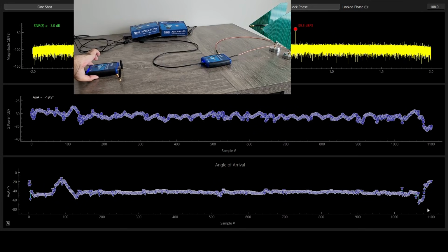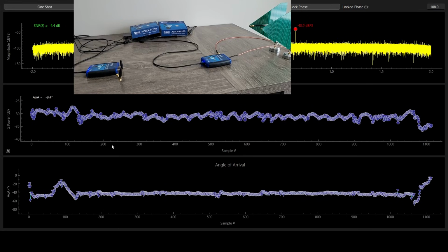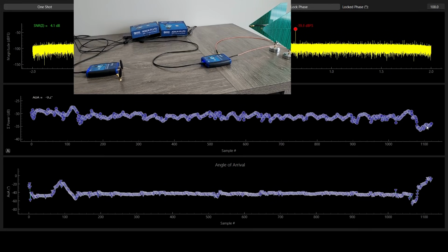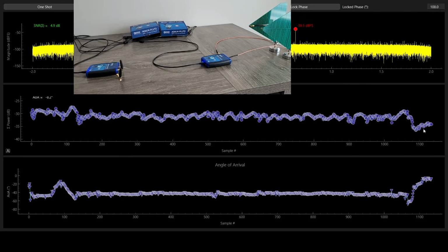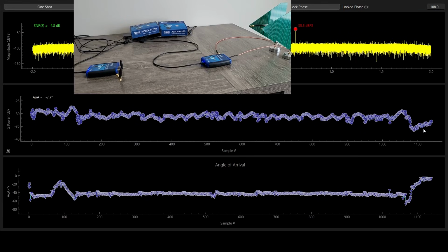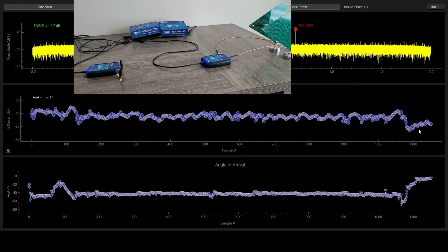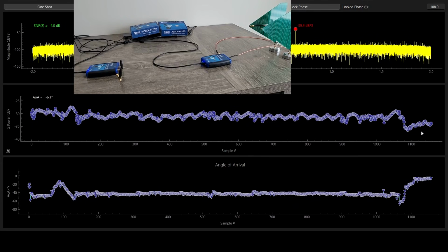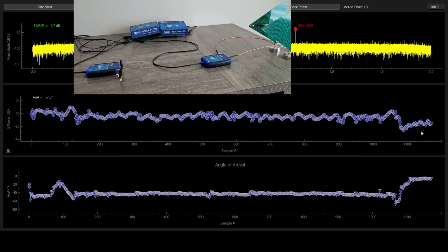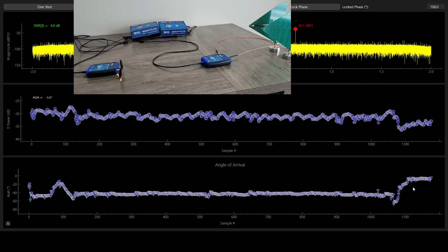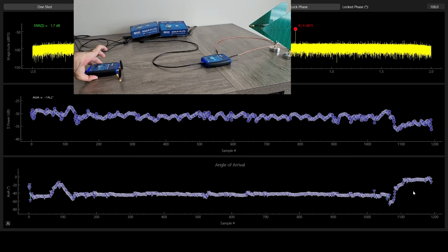And with it, what happens is that the angle of arrival has increased, and with it, the received power has decreased. This is because our loop is open after the initial phase alignment that we did through TX phase. Now our RX is not tracking anything from the TX side. We need to make sure as the position of RX is changing, we are changing with it. So we are tracking the information. We are tracking the TX beam.